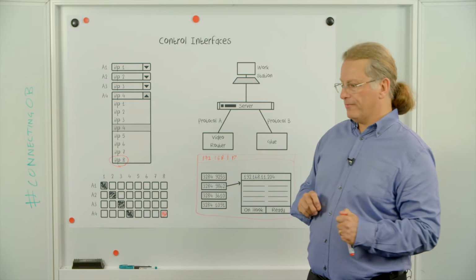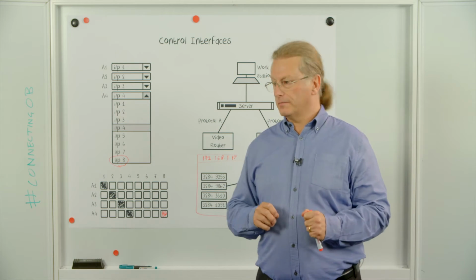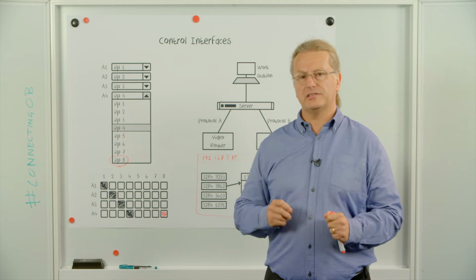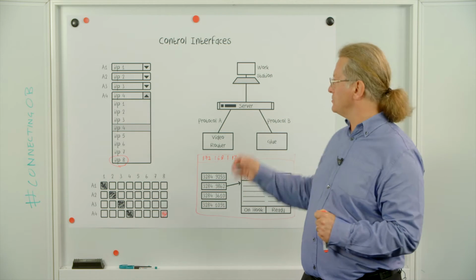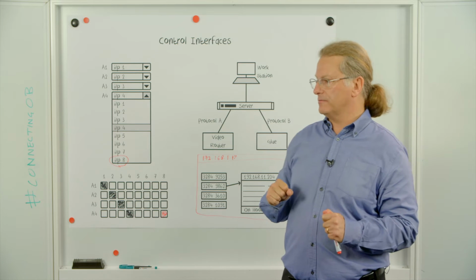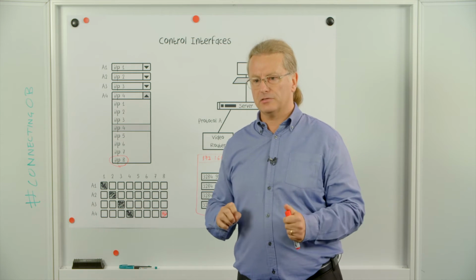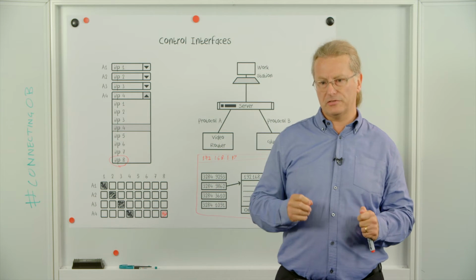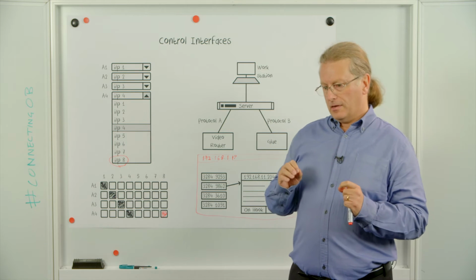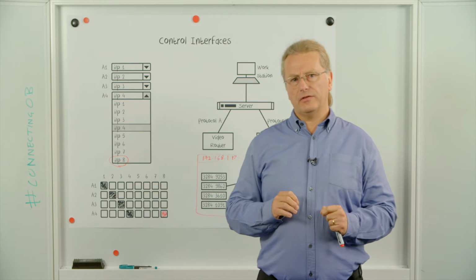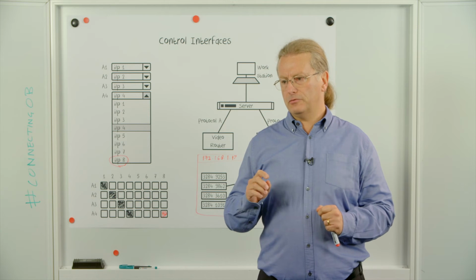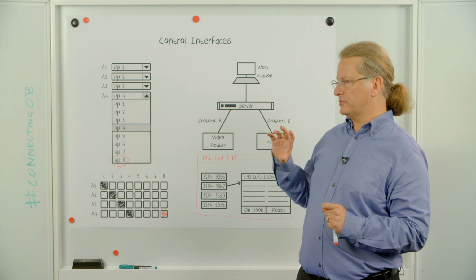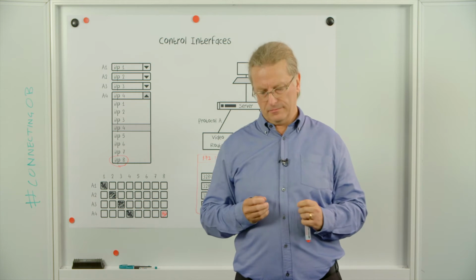The control system, therefore, has to talk to a whole range of different equipment using different protocols, and it's its job to translate those protocols into a familiar set of icons, button colours and graphics for the operators to interface with. However, in doing so, it shouldn't slow down the operation. The operators still need to be able to press a button and the system react to it very, very quickly.